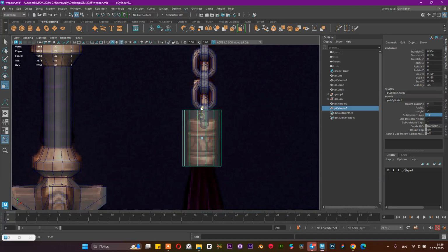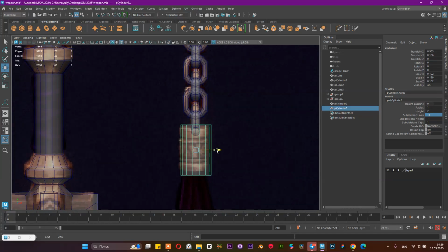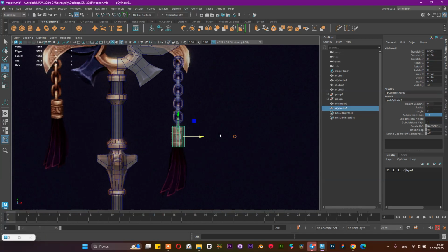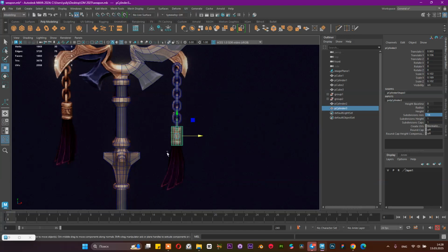And another interesting idea: if you have some feathers or transparent details, you can create one plane, and in the texturing process you can draw details with the transparency and apply the texture on just the plane, and you will get a nice feather, for example.